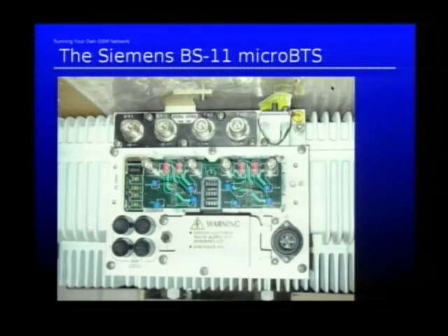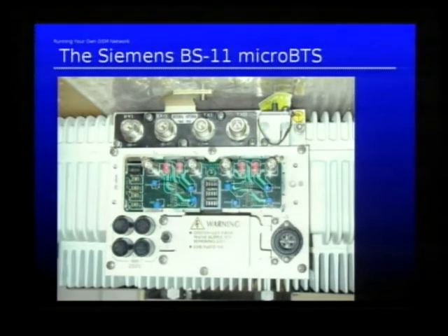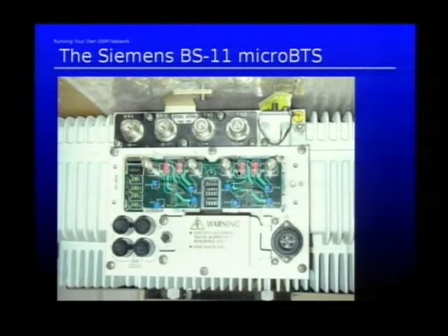This is the interface connection. Here on the top, we find the connectors to the RF antennas. We have 2 transceivers, so 4 connectors: 2 antennas for transmitting, 2 antennas for receiving. On the lower part, we have the E1 interface. Those are the coax-like looking connectors. There are two pins inside. It's not the standard BNC connector you might know from old Ethernet, but they contain two.